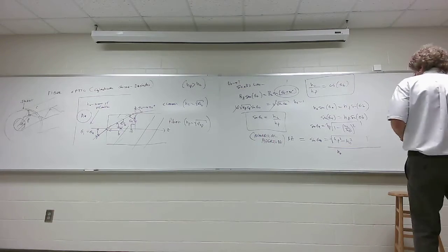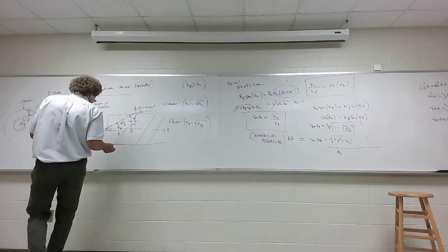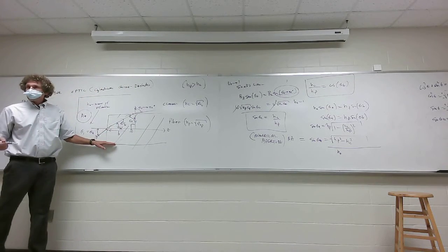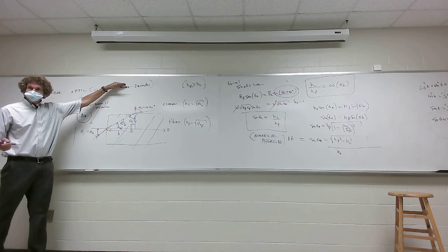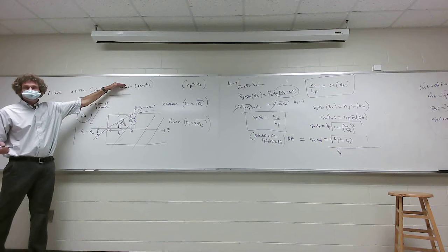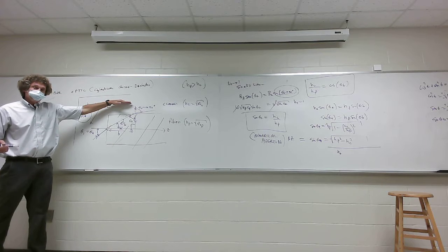Now, the fiber I'm showing you here is all fiber of a given index of refraction, then it's all cladding and then jacket, right? Thickness of the cladding is not of importance, not at all, really. I mean, it can't be real shallow, but the wave dies off fairly fast in here, the evanescent mode, and you don't have to worry about it.